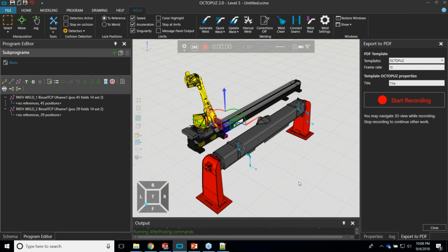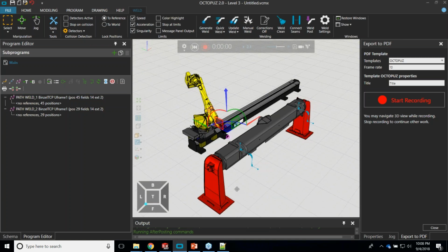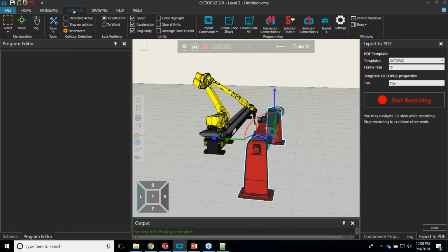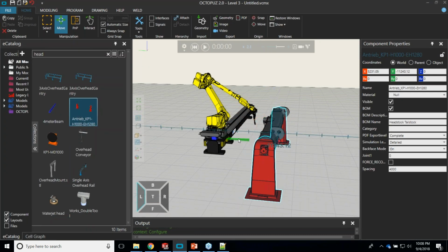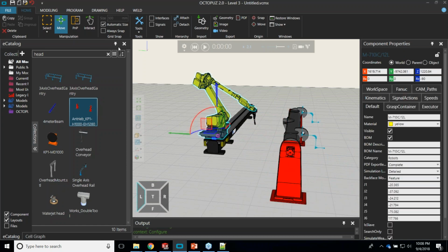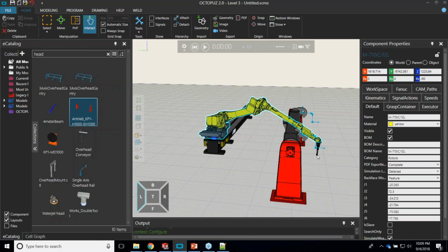Yes. The same rules are going to apply whether you're using offline software or not. We're going to be entering center of mass data into the software as well. So if you've got a really heavy tool, let me take this positioner and move it. If you're stretched out like this, obviously the further away from your base you are, the more variability you may experience, especially if you've got a heavy tool or a heavy payload.